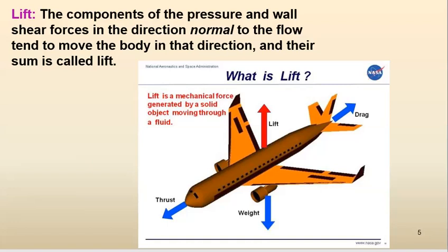Lift is a mechanical aerodynamic force produced by the motion of the airplane through the air. Because lift is a force, it is a vector quantity having both a magnitude and a direction associated with it. Lift acts through the center of pressure of the object and is directed perpendicular to the flow direction.